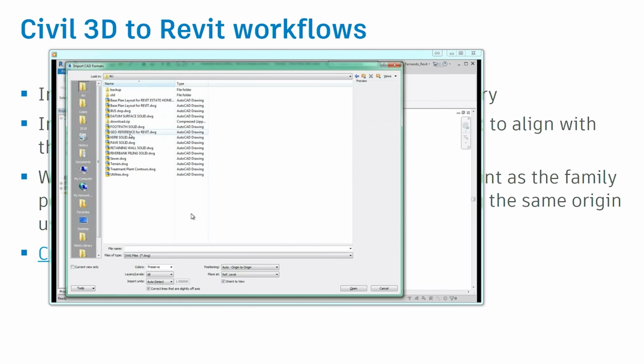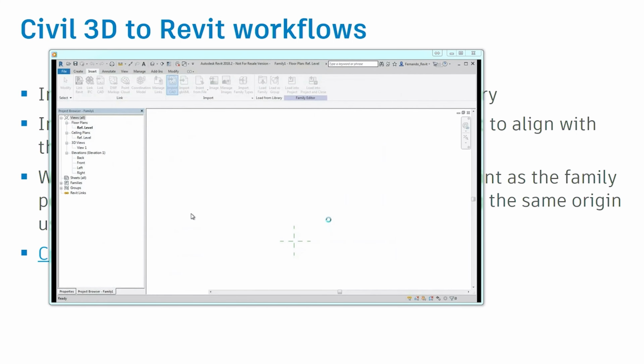You're going to see it, it's a very easy process. Grab the file, insert. Here I'm going to do it manually. There is no current view only. It's a solid object, I want to see it in 3D. There are no issues with scale. Everything is smooth. Go, manually, origin, put it there. Sometimes I use center, it's more sure. We never know where the origin came from. So the file is there somewhere. It's loading. And we do a zoom extend, and we're going to see that part of the surface somewhere on our screen.